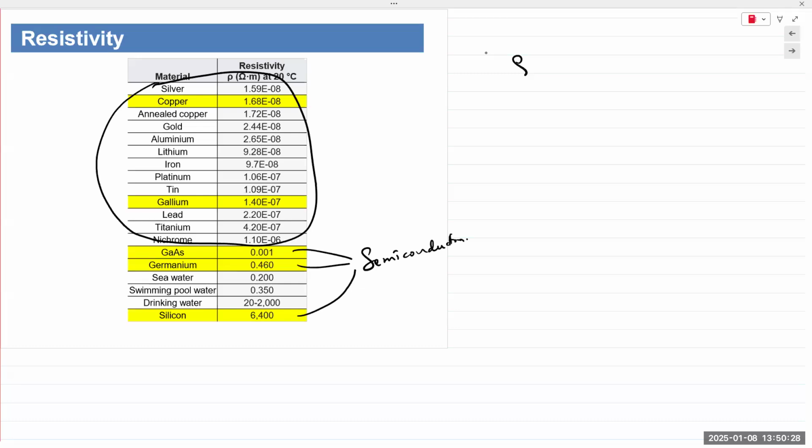You all with me so far? In this energy band diagram, without making it too complicated, we look at two things: valence band energy and conduction band energy. The outermost shell of an atom is known as the valence shell, the valence band. The electrons occupying it are known as the valence band electrons. They have the valence band energy. Silicon and germanium, as you said, are from column 4 of the periodic table, so they have 4 electrons in the outermost shell. You need 8 electrons to form a covalent bond and a stable atomic structure, right?